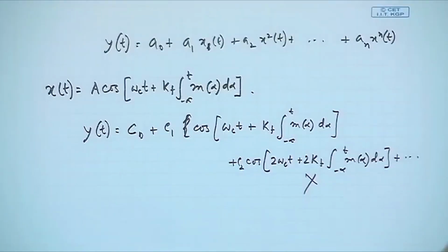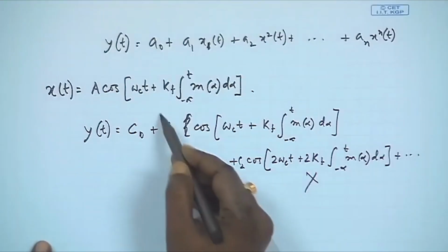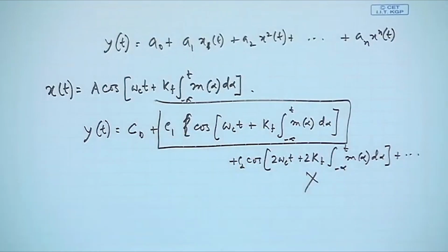So, it will have a band pass filter centered at omega_c, and the band will be just the FM band. If I pass it through that band pass filter, all those higher frequency terms, where the frequency deviation is getting twice, thrice and so on, will be cancelled out. I will only have this particular thing.